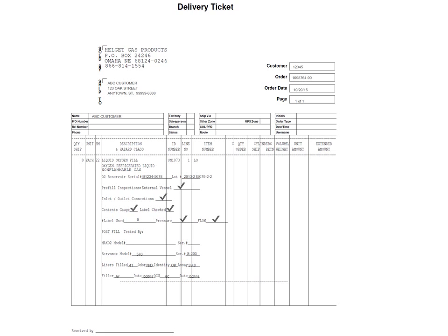Again, we have our lot number. It is the same configuration. The truck with a dash, then a branch, the year, the reverse Julian date, the number that the liquid oxygen supply vessel represents. In this particular case, it was the second one filled on the 79th day of 2015. And the last digit represents the number of fills off of that supply vessel. In this particular case, this reservoir is the second fill off of the supply vessel.